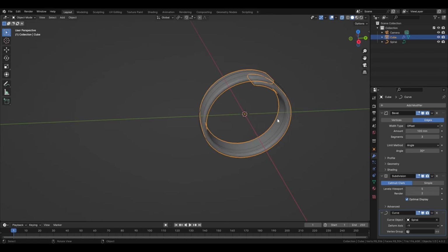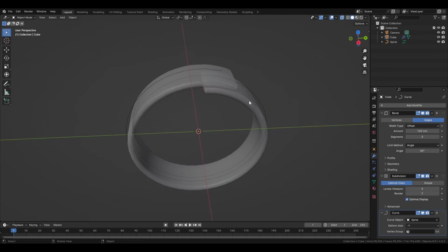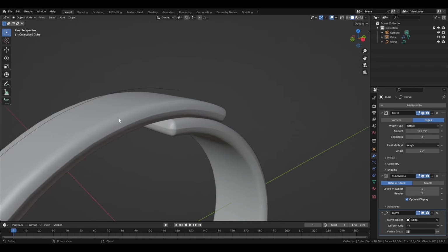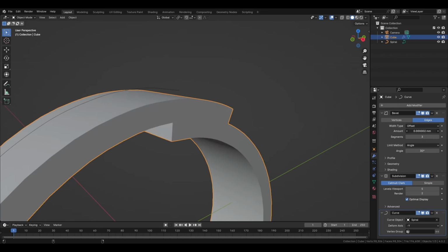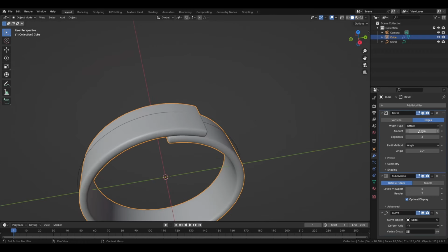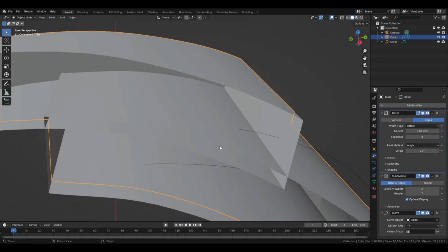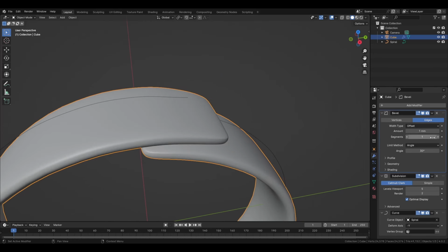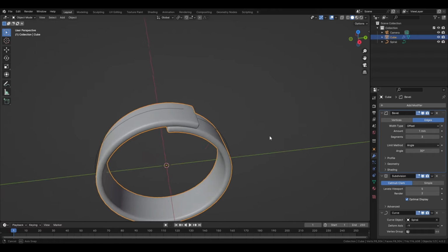You can add more subdivision to have something nicer like this, and remove the wireframe, the X-ray mode or transparent mode. And you see there is a line here, and so if you do this, if you reach a smaller point, so press Shift and go closer like this, you see that there is a value at which it's actually better. In order to do smaller, you would have to type it manually. So for example, 0.1. I mean, this is ridiculously low, so let's keep it at 1 here. You can also change this and see how it reacts, how it changes your mesh.